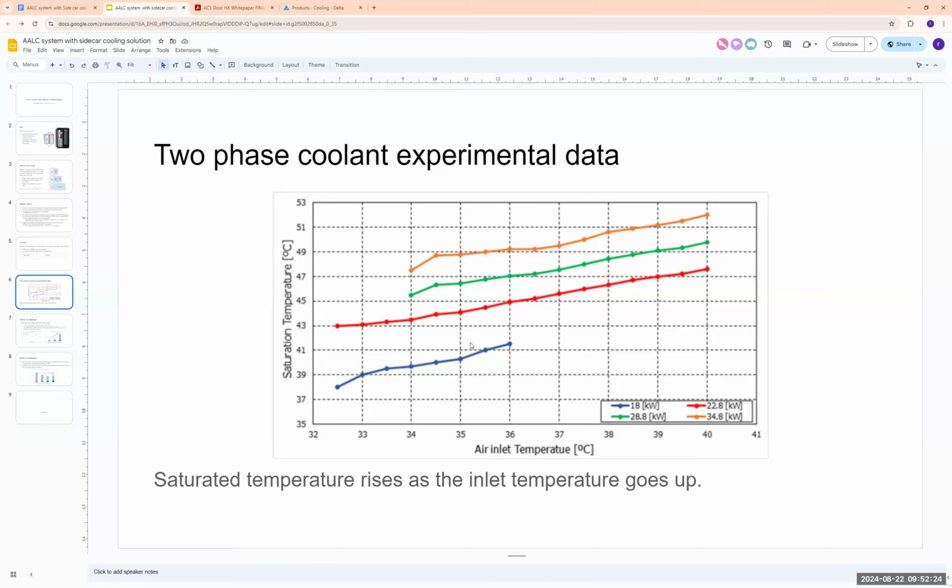It has some advantages. One of the advantages that I have seen is that for the same heat exchanger surface area, two-phase can reject more heat than single phase. I'm not pretty sure. It depends more on the technology. For example, microchannel: only if you change to microchannel, you get more power. But not because of one phase or two phase. This is because microchannel is better than fin and tubes.